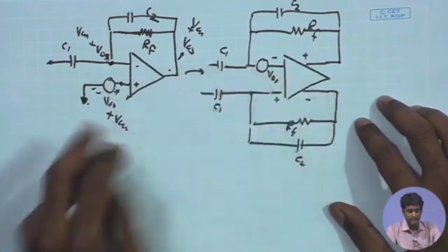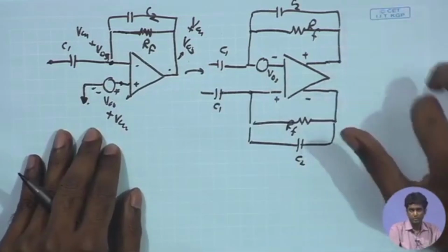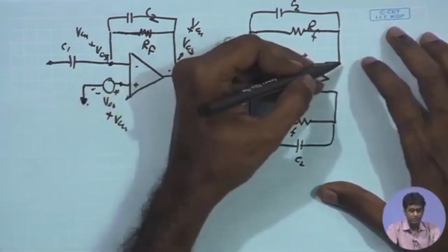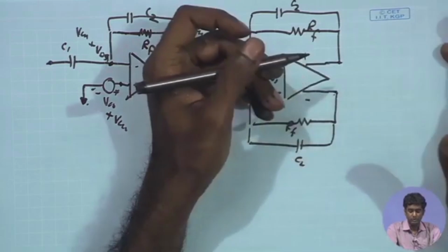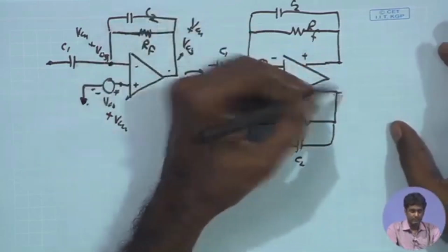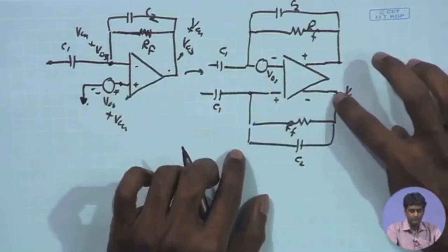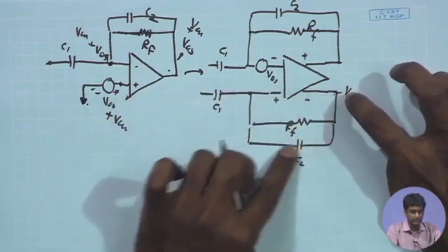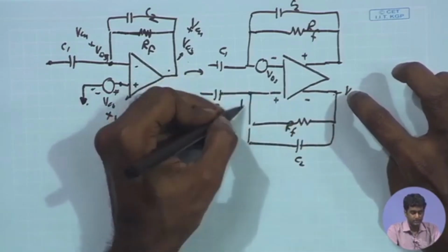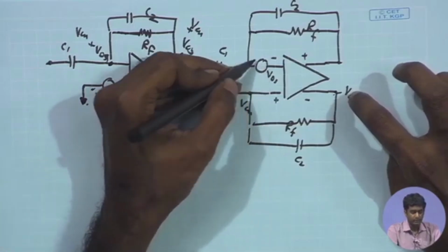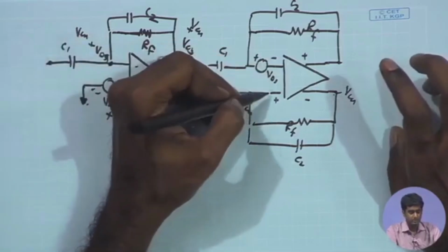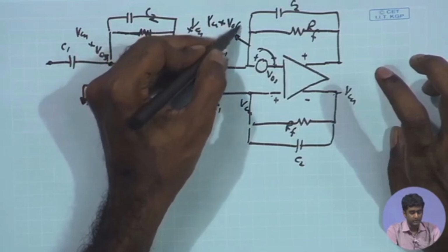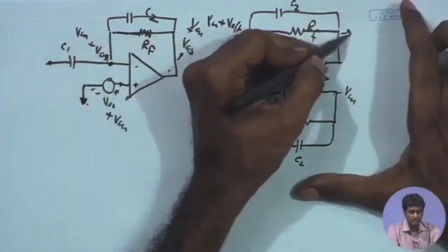If I assume that the output is controlled and you have a VCM at the output, then the overall amplifier output common mode is going to be VCM. Suppose this particular output is set to VCM. Once again, because of this resistive feedback, you do not have any AC or DC current flow through this capacitor, so this has to be VCM. However, if I take the polarity of the V offset in this fashion, this again has to be VCM, and